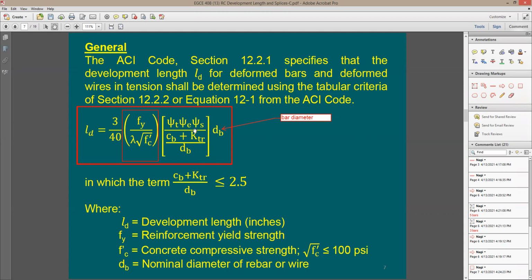Did you guys hear before about epoxy coated rebars? Just for curiosity. What is this used for, Mike? Slow or inhibit corrosion. Exactly. So when you have a corrosive environment, one of the options is to use epoxy coated rebars, because the epoxy is going to be delaying the corrosion, right? Yeah, but I've also been told that it makes them, for lack of the right term, more slippery. Exactly. This is a very good point.